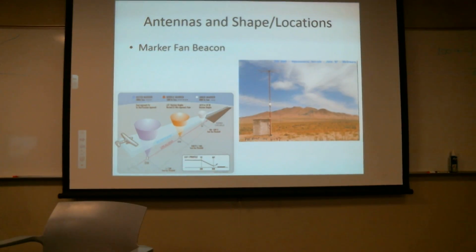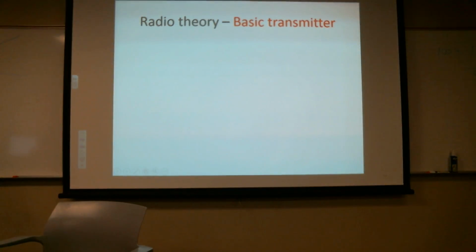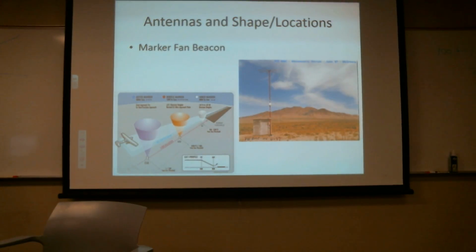They call that a fan marker, and it's a beacon because it's just beeping, but doesn't really give you any other information. Are they phasing those out? Oh, absolutely not. Really? No, that's part of the ILS. There are places where you don't need it anymore because a lot of folks have GPS, and the predominant users are using DME or other types of equipment. But there are still many airports that use them.